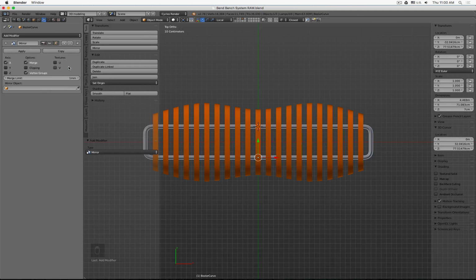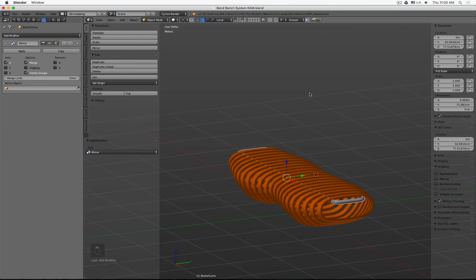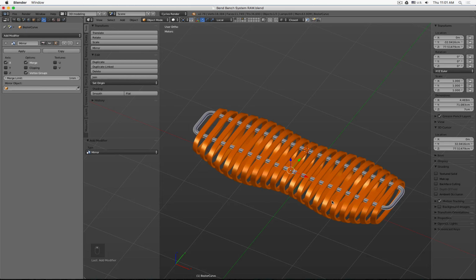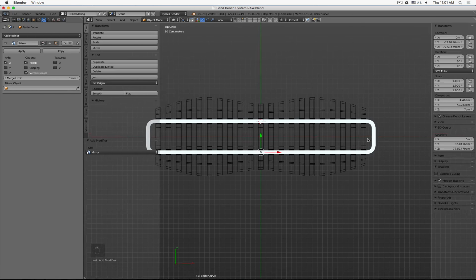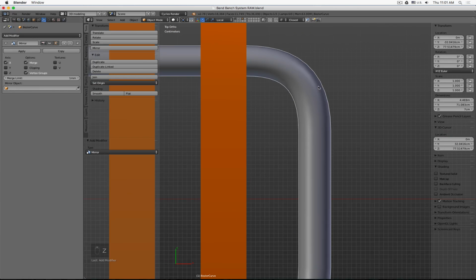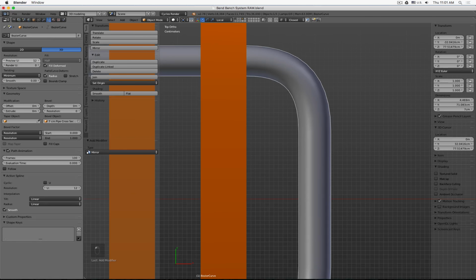But essentially you can memorize it as well. If we have one pipe, another pipe has to go in, or elements, you want to have a tiny space so the elements don't wiggle or move, but it's easy to move them through. So sometimes you don't work with the exact dimension. The hole can be a tick bigger than the element that is being inserted. Okay, this all looks pretty good.